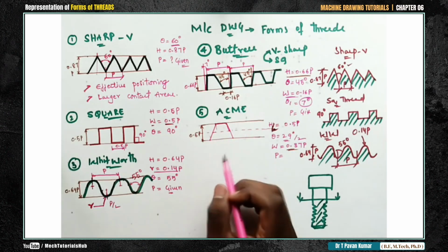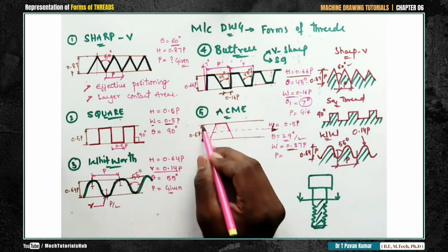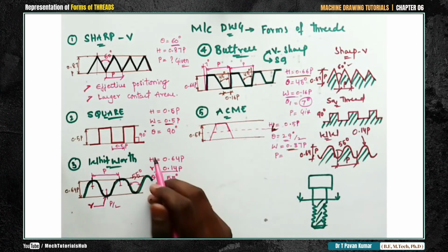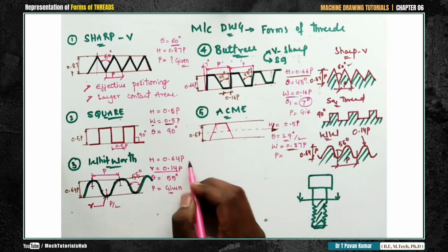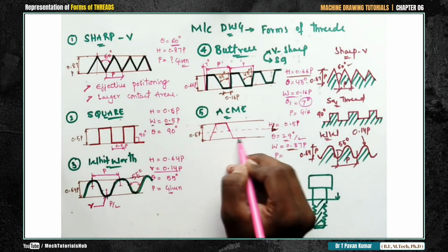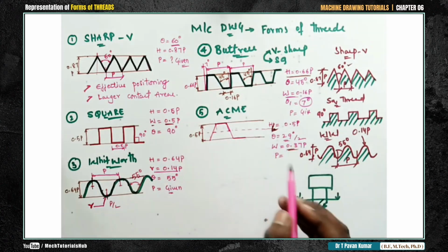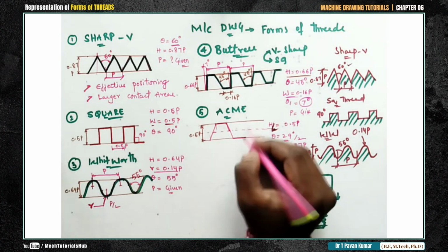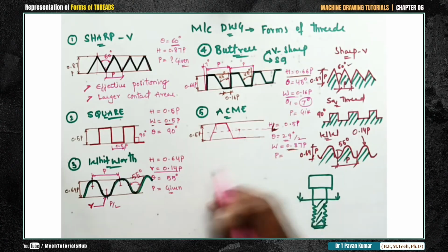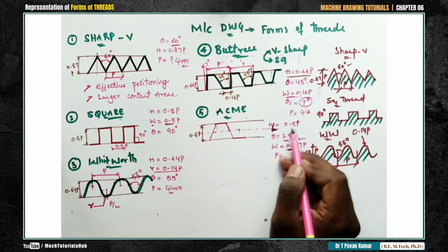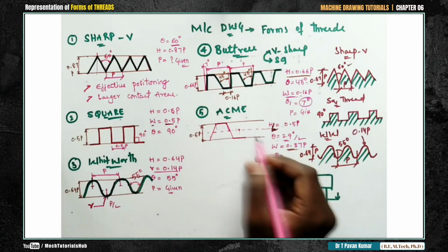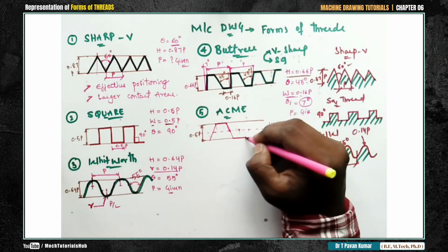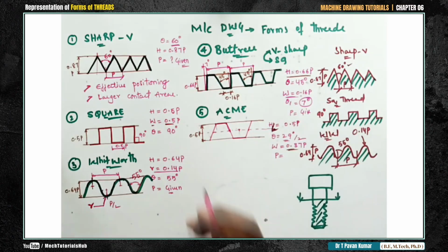So if you want, you can calculate or you can draw an inclination line by considering the angle, or else you can consider the height also equivalent to the width of the threading center. This height is equivalent to the width of the threading center. If you could manage with that width also, you can draw the sketch. Again this is 0.37, again there is an angle of 14.5 degrees. Okay, now try to darken the required portion. This line is important. Use an HB pencil, HB. Darkening the required portion is also very much important. Okay, don't bother about the 2H lines, let them be, don't erase them.